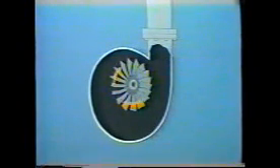Let's look at a drawing to see how a centrifugal compressor affects the refrigerant vapor. This is a representation of the impeller in a centrifugal compressor housing. The impeller is an important part of the compressor. It makes the vapor move. It's a large disc that's equipped with a number of radial blades. This blade arrangement is the impeller. It's located inside the compressor housing at the intake nozzle. The impeller spins or rotates very fast. It can be driven by an electric motor or a steam turbine.